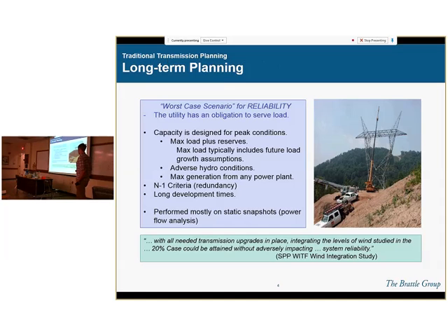This is conventionally how we've performed transmission planning. You do a few scenarios for maybe different load scenarios, high load, low load, maybe seasonal, and you arrive at the least cost portfolio of transmission projects that will allow the reliability criteria to be met. And these, as Terry mentioned in his presentation, are loss of load probability in any hour or expected unserved energy.